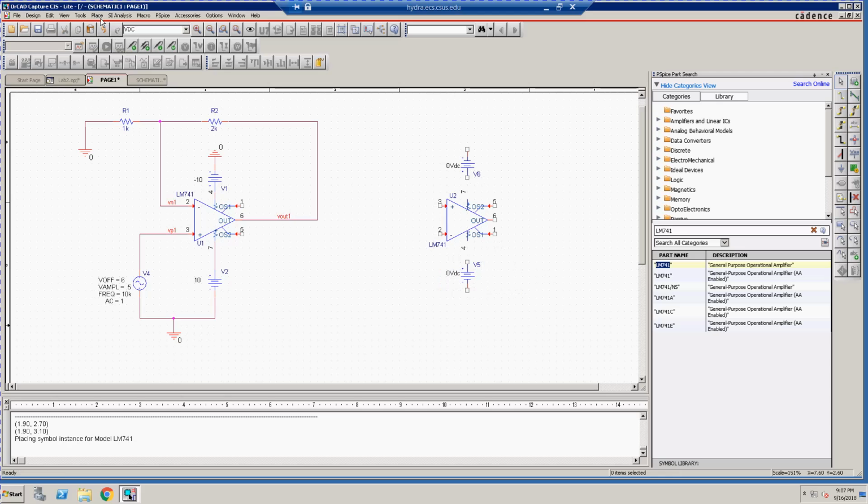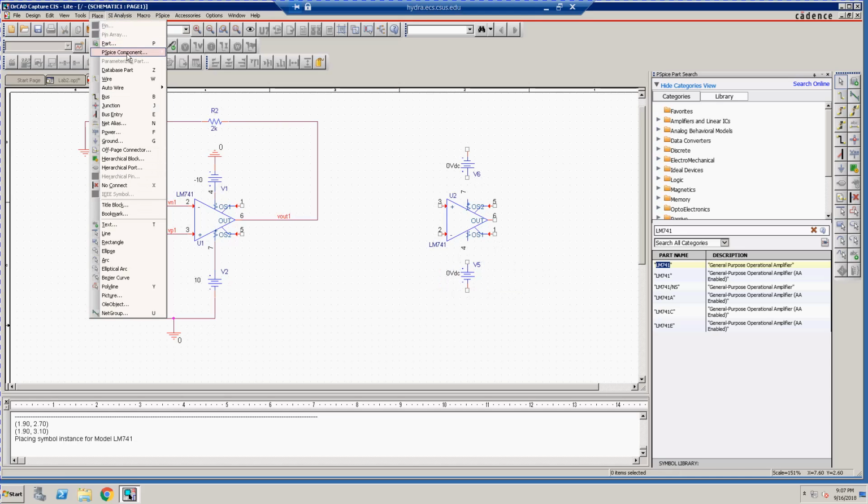The next thing we're going to need is resistors. So again, PSpice component, this time we can just come down here. For these labs, we're just going to use ideal resistors. If you wanted to use resistors that you would actually purchase to have placed on a PCB, you could go down to source and search for them.